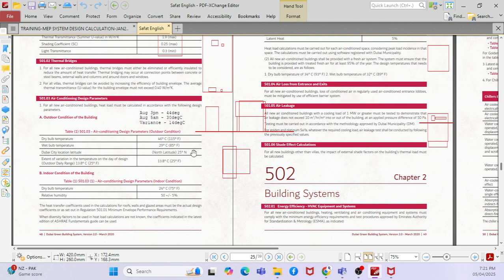For example, for lighting load, you can take 10 watts per square meter or 15 watts per square meter. And if you go to an office area, it depends upon the type of office: there is light computer, medium computer, heavy computer. Depending upon the computer, they will tell you the heat dissipation, 5, 10 or 15 watts per square meter. Based on that, you do the calculations. Now we will start with the thermal load calculations.